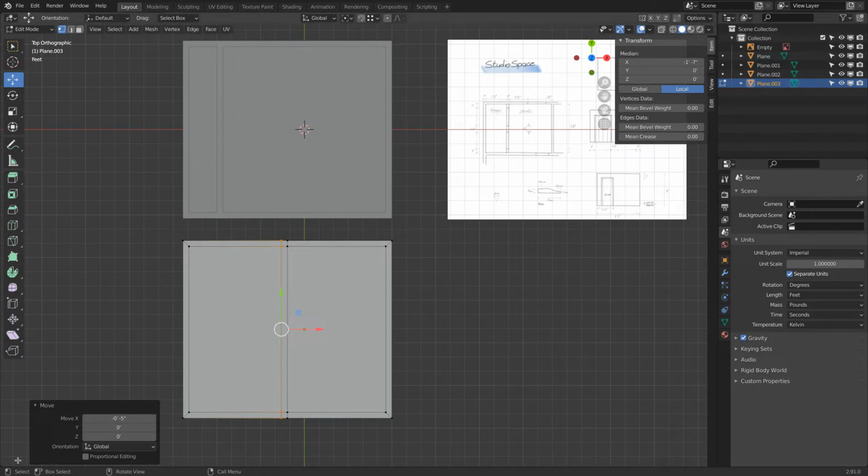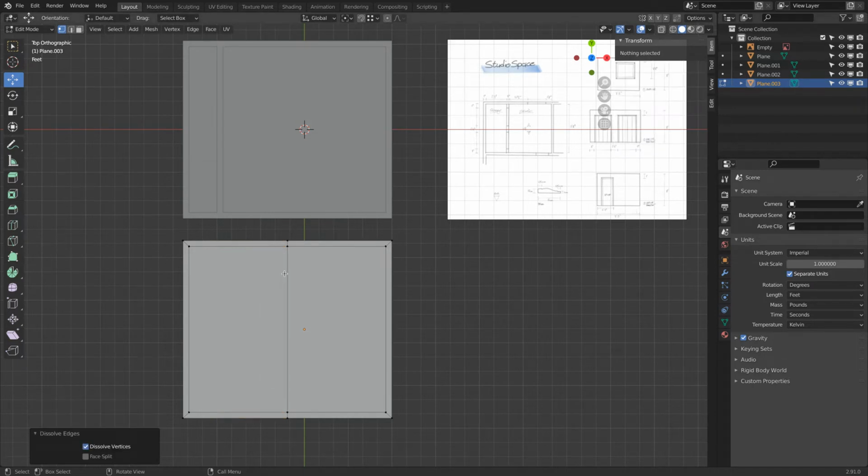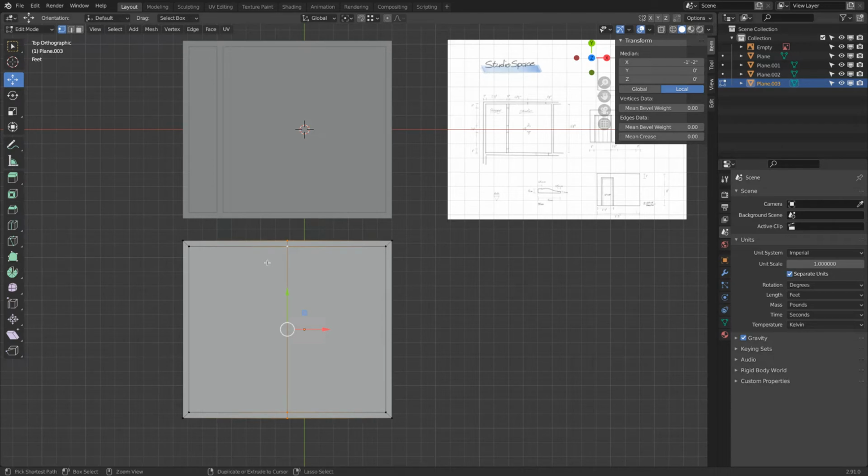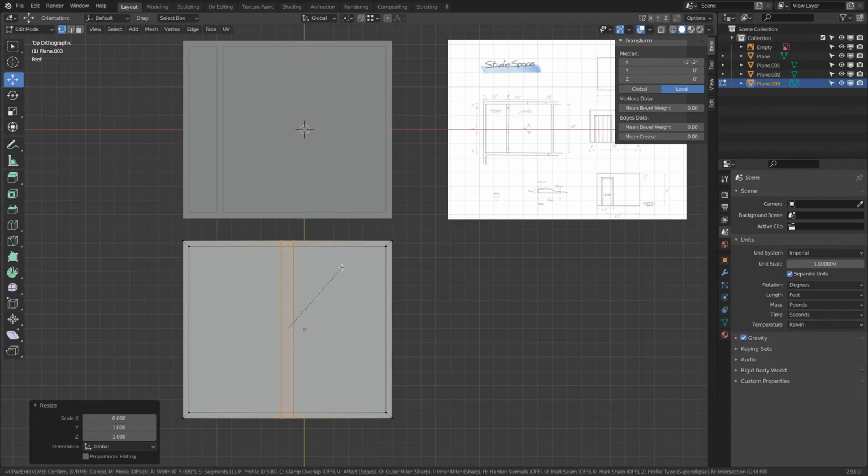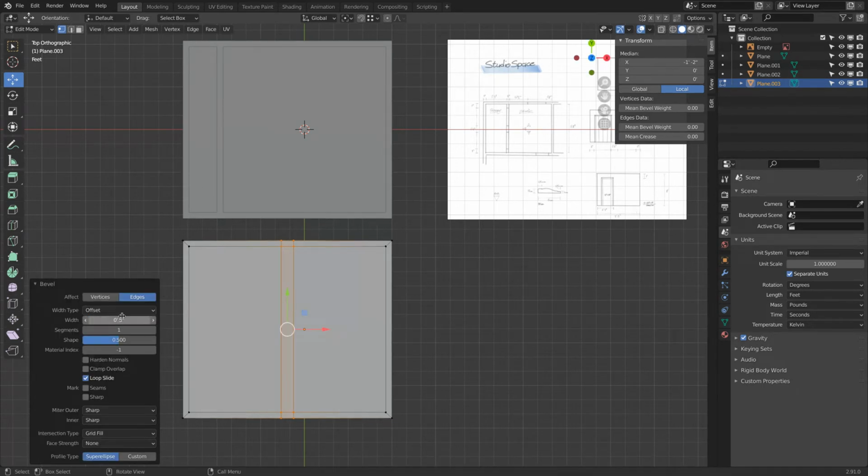Was a little bit labor intensive, so let me show you a better way. So just to make sure that when I press Control R, you see the yellow line is really straight, SX and 0, so it's nice and straight. And now Control B, I simply bevel it to 5 inches. There we are. No, 2.5 inches, because it's a bevel, left and right is then the diameter, because the width for a bevel is the radius, but we need a diameter. So half of 5 inches.